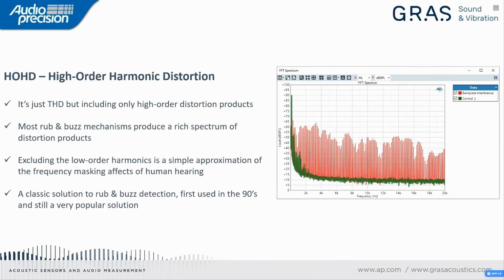solution. And this is, as I've mentioned, high order harmonic is available with log chirp. You will get results, but it is only supported up to the 20th harmonic. So high order harmonic distortion is best used with a fast sweep, as you get much higher harmonics included in the result.